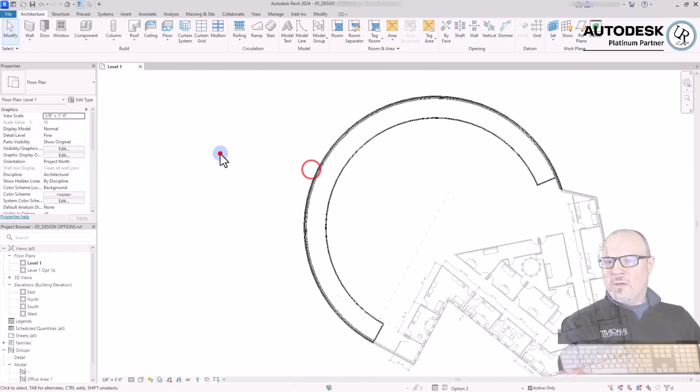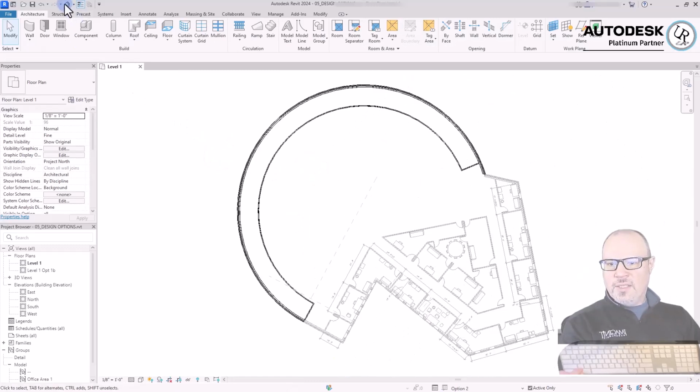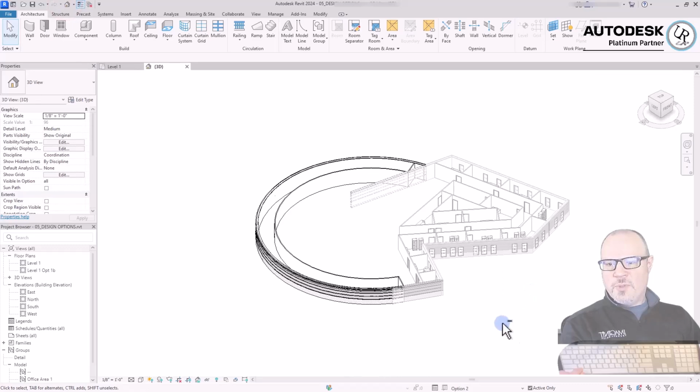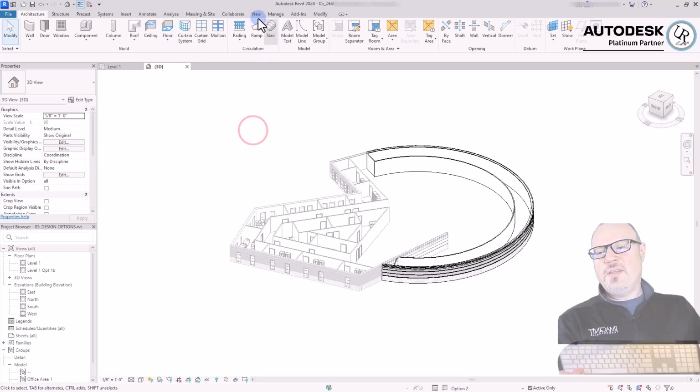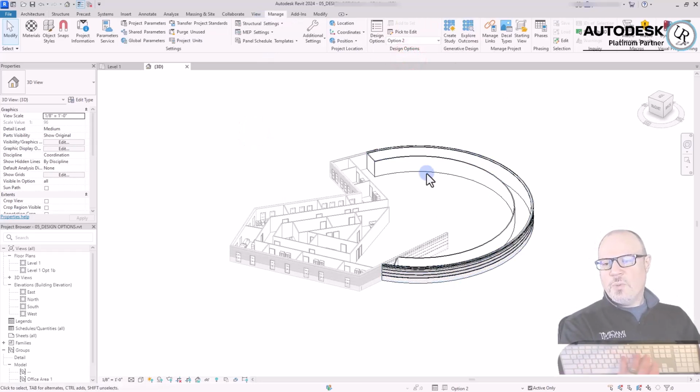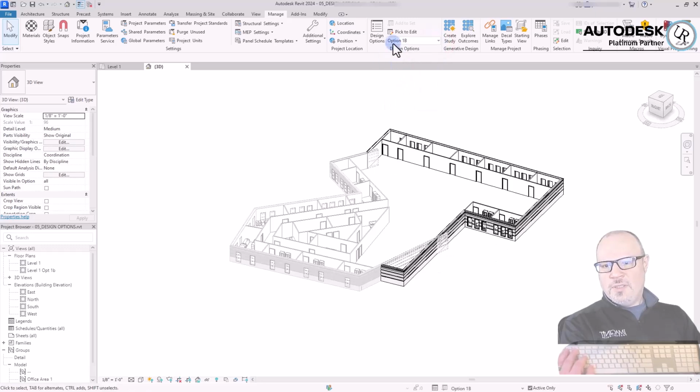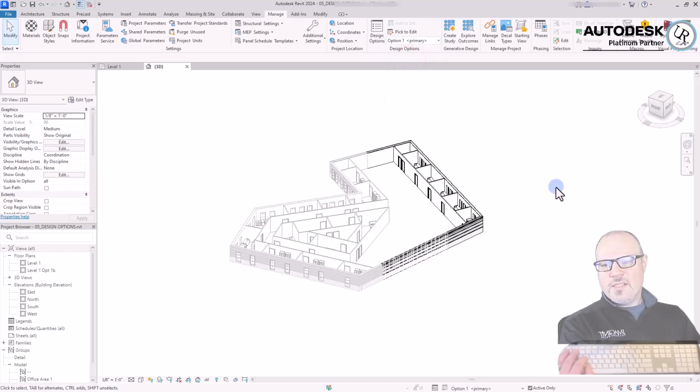The design options are also three-dimensional. Again, they are a completely designed building. As much information as you put in the design option will be available in that project. You can create a design option that is simply as different as a door swing or as expansive as an entire wing or multiple stories of a building. The options are limitless, but the amount of information that is included within each design option is stored in the project model and will impact the size of the project file.